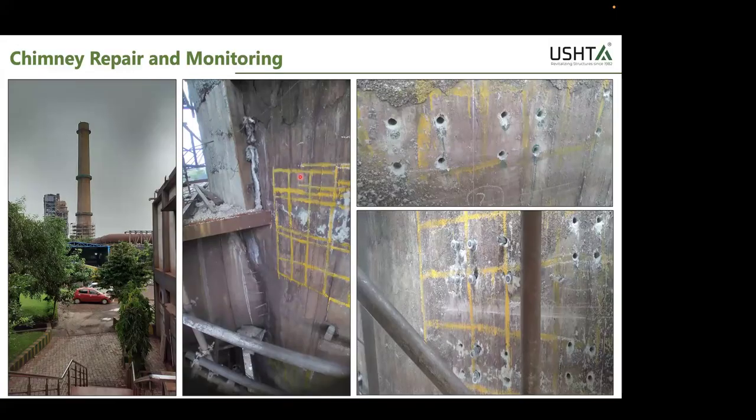How it works is on the principle that every metal has a different dielectric constant. So when you scan, the reinforcement will show parabolic shapes. By that we can identify the location and the probable size of the reinforcement and the cover depth as well. Based on that, we selected locations for anchors, and we drilled almost 4,500 anchors, none of which punctured the steel. So whatever steel was residual, we maintained that.